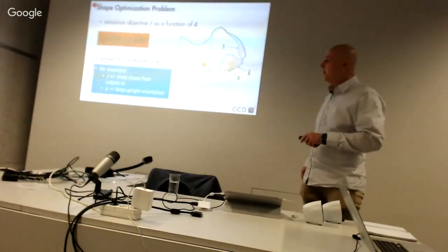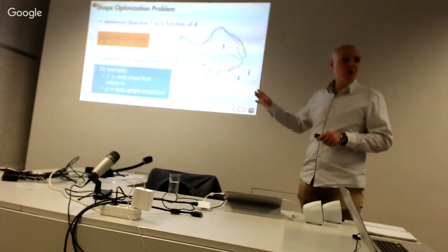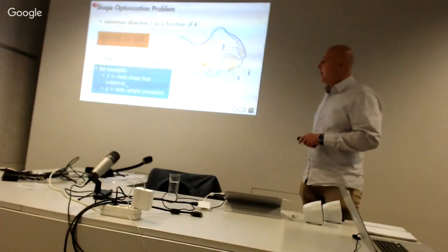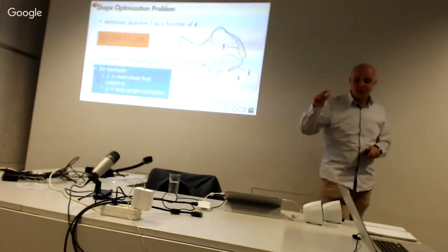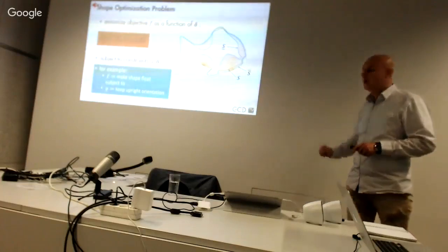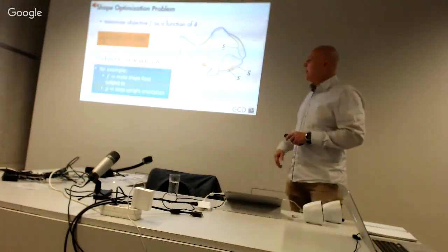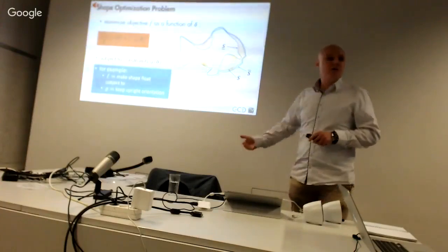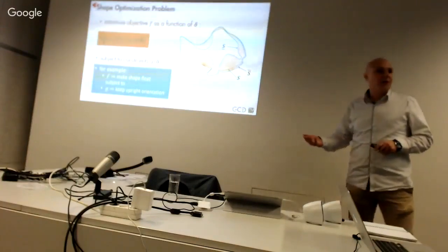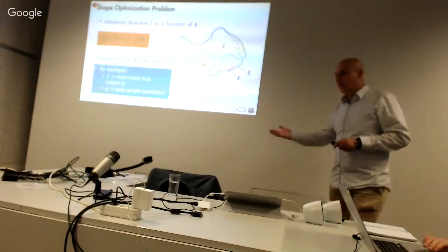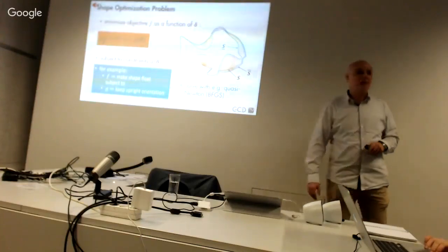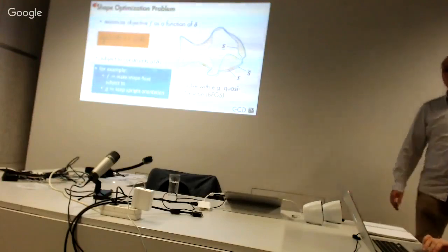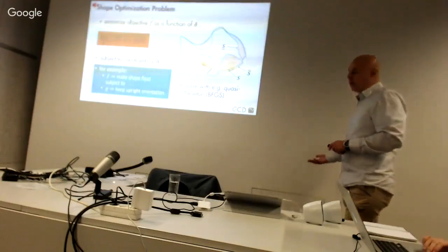The objective function f could be, for example, make the shape float, subject to some constraints like keep upright orientation, and also box constraints like keep minimal thickness of the material and so on. This is something we could plug into state-of-the-art numerical software, like, for example, MATLAB's fmincon. We can solve it, for example, with a quasi-Newton nonlinear solver, and basically it would work.